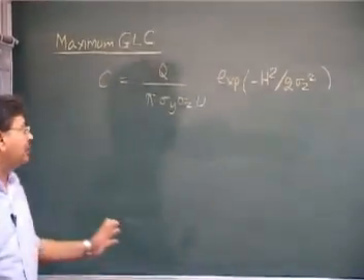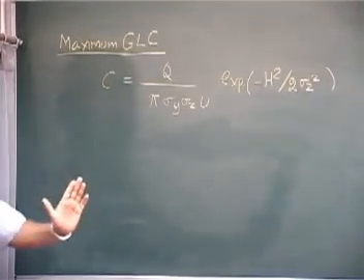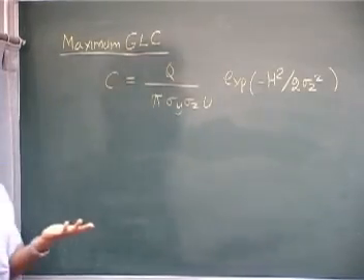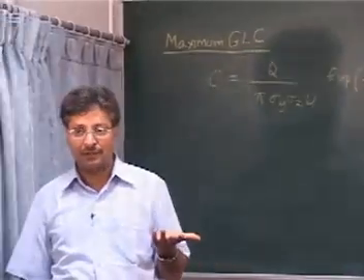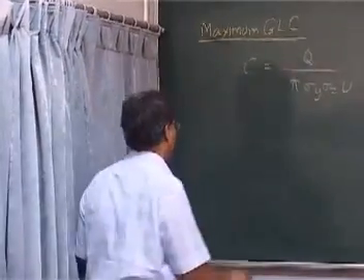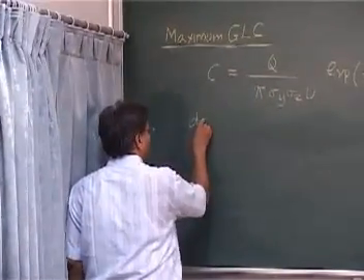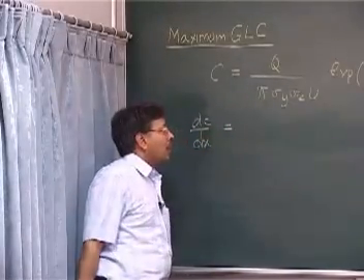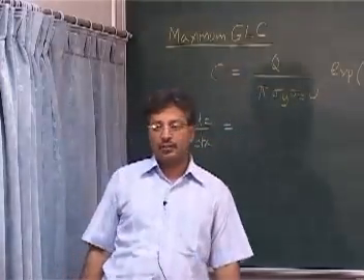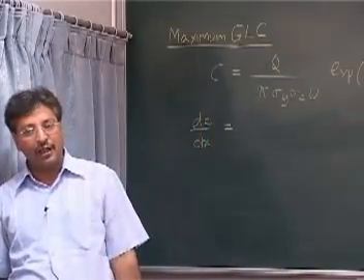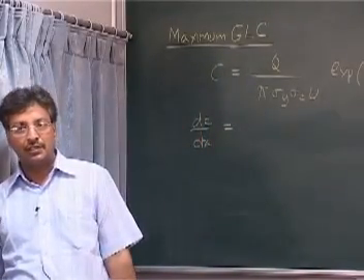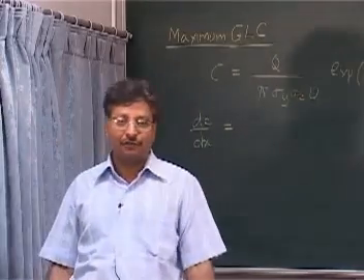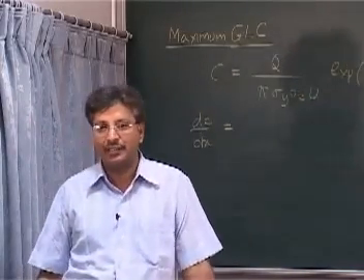Obviously I want to find the maximum concentration with respect to my downwind distance. So, I can differentiate this function with respect to x. And what are the things which are functions of x here? Sigma y, right, sigma z. Is h also a function of x?